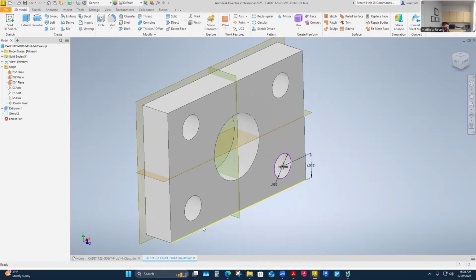Once I constrain to a plane, yes, it locks it down, but it still opens the door to the part can still kind of rotate. And we could explore this on a part. You could spend your time just doing a simple block, doing one constraint in an assembly on a plane, and you would see that I limit some rotation now by hooking it to a plane. But it still will slide on other planes maybe, and so it takes constraints to these three different planes to really lock down its degrees of freedom.